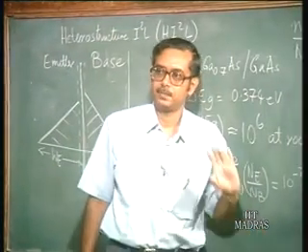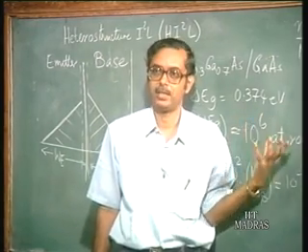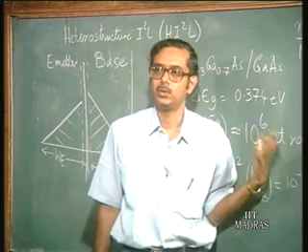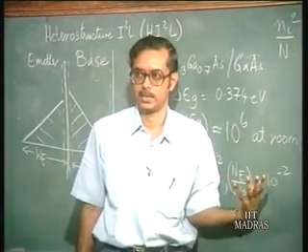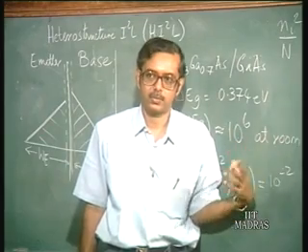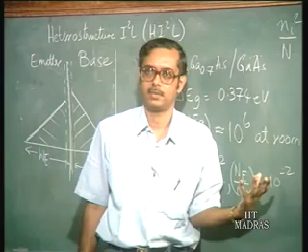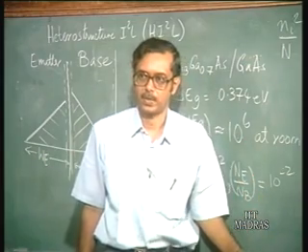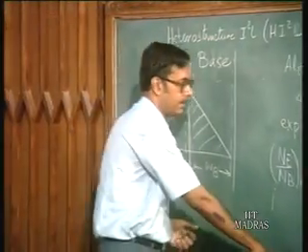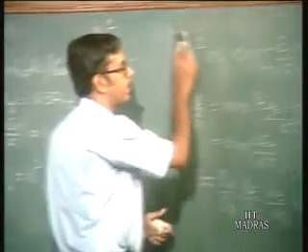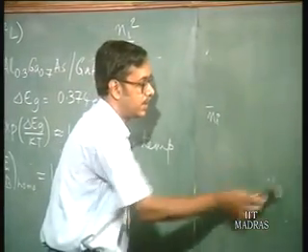So, this heterojunction has been used in I squared L to improve the speed performance of I squared L circuits. In fact, a lot of recent work on I squared L which has come out has been in this area of heterostructure I squared L. And you can see why you should have a better performance if you use heterojunction. I think it is clear now.